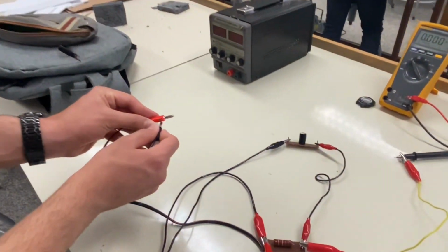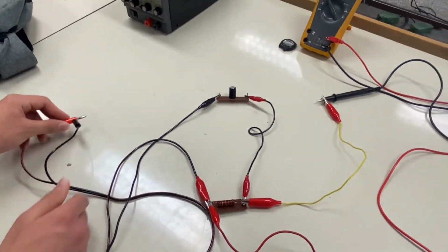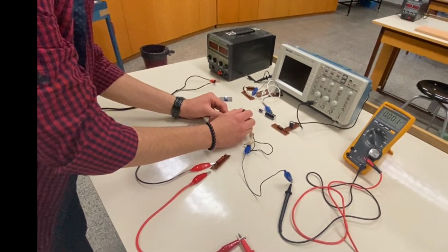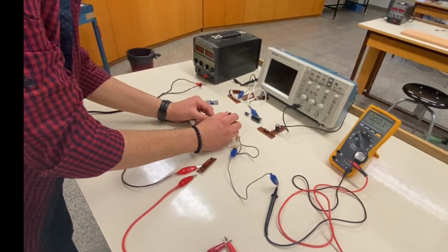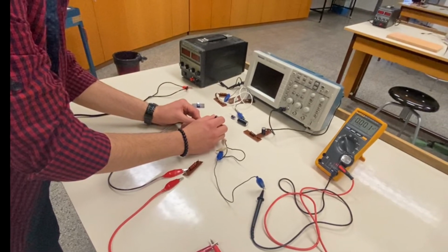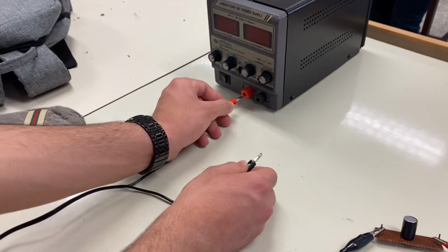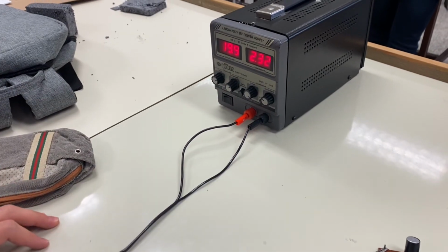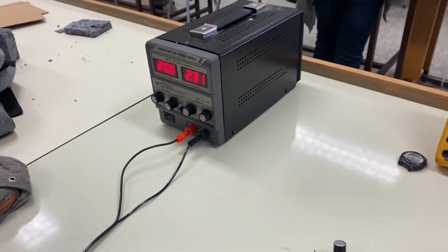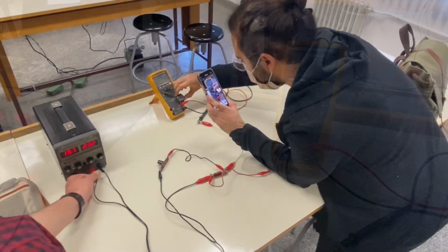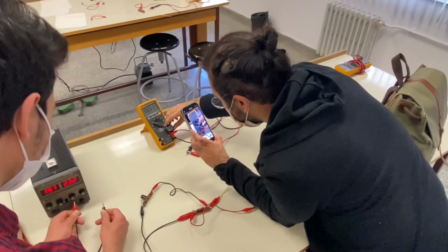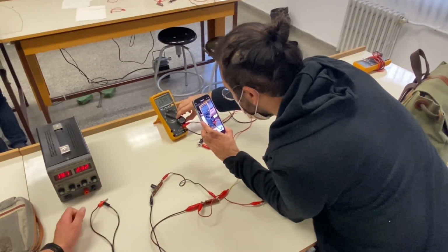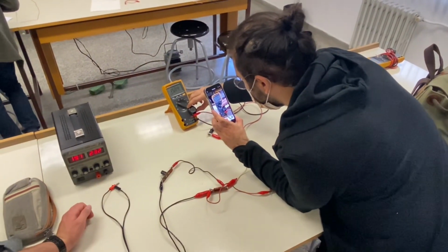First, I discharged the capacitor by connecting its terminals with a crocodile cable, and I connected the capacitor to the resistor and connected them to a power supply, all of them in series, and attached one multimeter to the resistor in parallel. Then I set the power supply to 20 volts and waited for the capacitor to be charged. After waiting for the capacitor to be charged, I disconnected the positive and negative ends which were connected to the power supply and created an RC circuit.